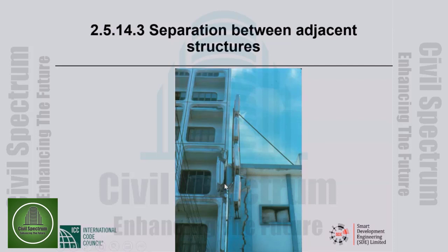The taller building, it is not very visible, but this is a dangerous situation. If the floor hammers against, let us say, the mid height of the column, sooner or later the column is liable to give. If, however, the floors were aligned, this floor were here, then the heavy floor would hit against the heavy floor, which is not the best situation, but that is unlikely to cause unacceptable damage. That is unlikely to cause something like collapse.